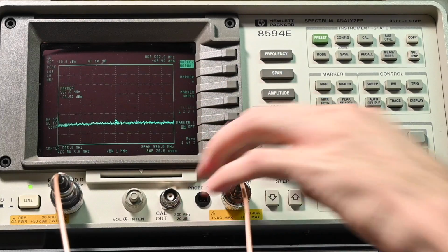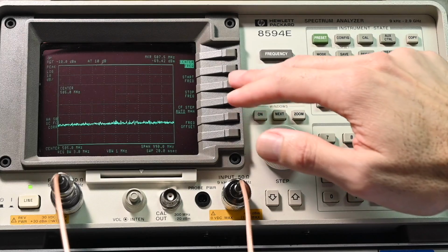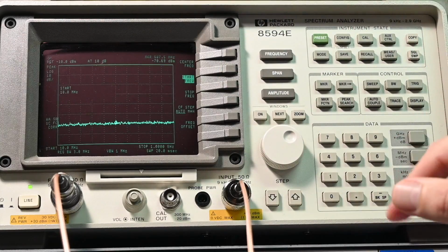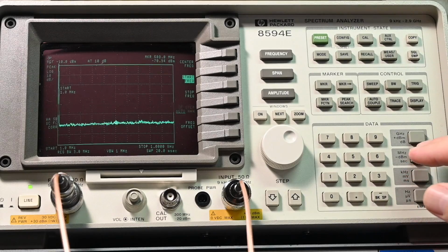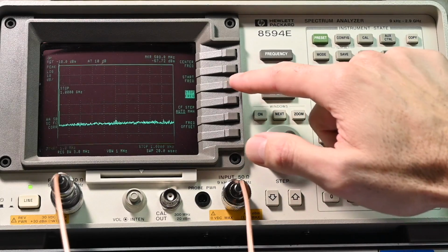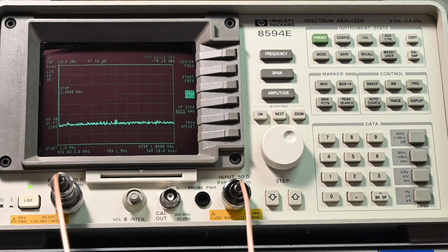So, okay. I think for the frequency we can sweep, let's do a start at, let's say, 1 megahertz. That should be perfectly fine. So we'll go 1 megahertz. And let's stop the sweep. Let's just do it at 1 gigahertz. I think that'll be okay. The low band extends a little bit higher than that, over 2 gigahertz actually, but this will be okay.